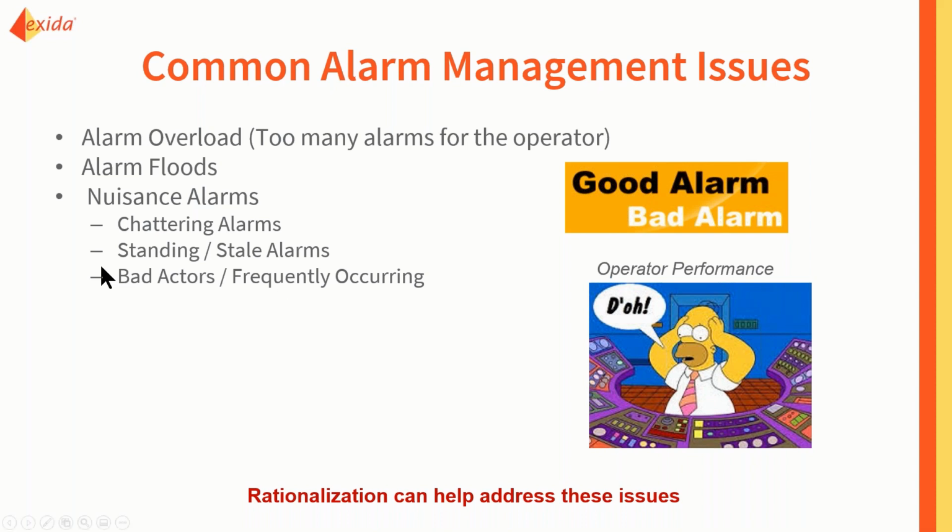And there might be chattering alarms, related to the re-alarm rate, where within a short period of time it alarms and then comes off, alarms and then comes off, on and off very frequently, which is a nuisance to the operator. Put yourself in the position of an operator looking at an HMI interface: you realize there are a lot of problems with chattering alarms or standing alarms, such that you can't really manage your alarms